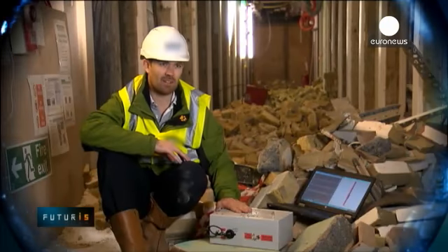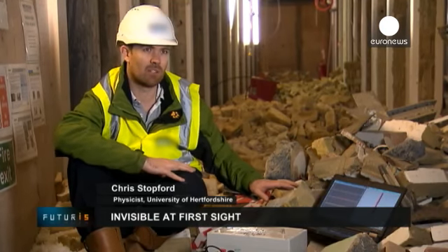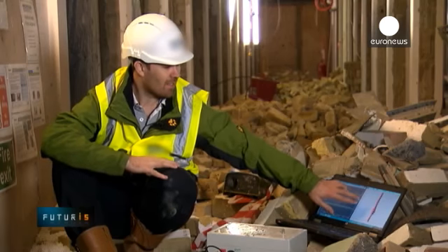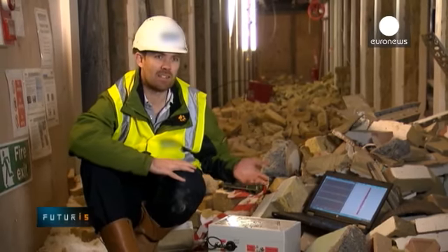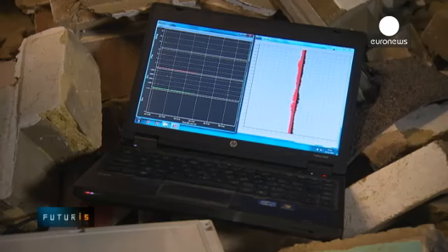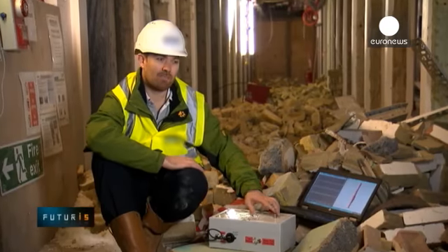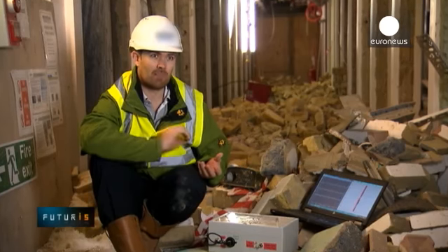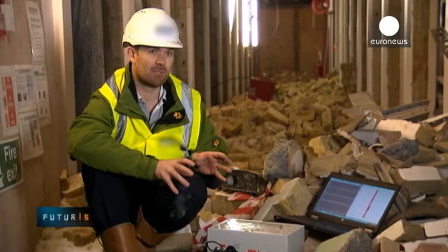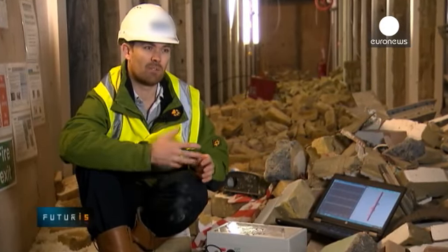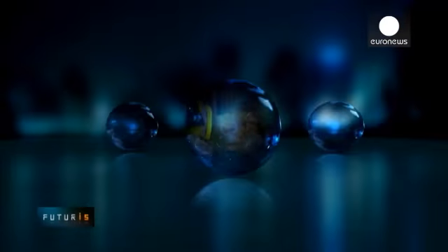This is our prototype asbestos detector alert. It's currently plugged into a laptop, which does all the data recording and manipulation. This is displaying the scattering pattern from every particle that goes through the instrument. In here it's quite dusty, but it's random dust rather than being fibrous, so we're not seeing any fibres at all. It works by drawing air in through this inlet into a chamber where a particle is illuminated first by one laser, and the scattering pattern from that is captured. It's then exposed to a magnetic field, which preferentially rotates asbestos fibres against non-asbestos fibres.